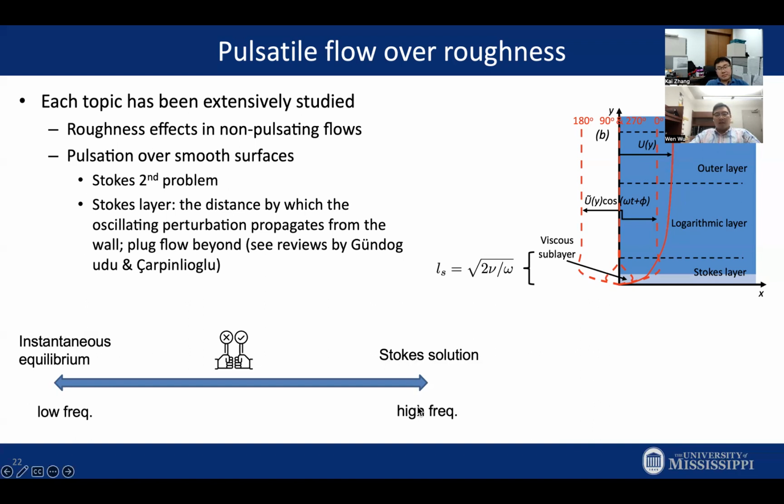On the other hand, if it's very high frequency, then the Stokes solution can be used to characterize the wall shear stress and near wall flow. But in the middle, between very low and very high frequency, there are still debates. Okay, even for pulsation over smooth surface.